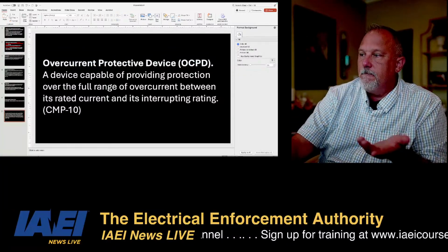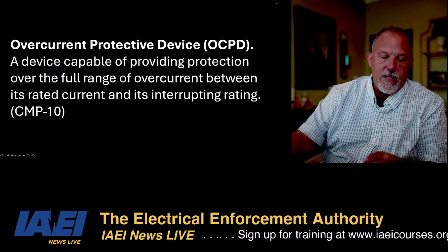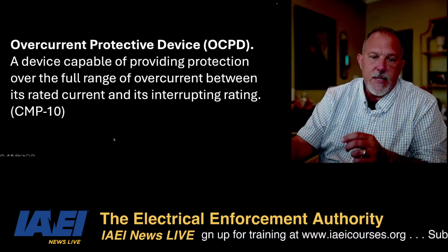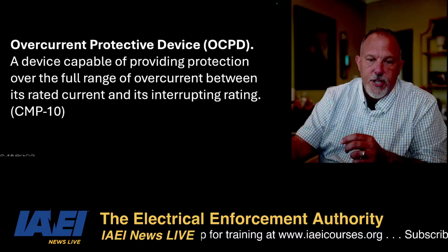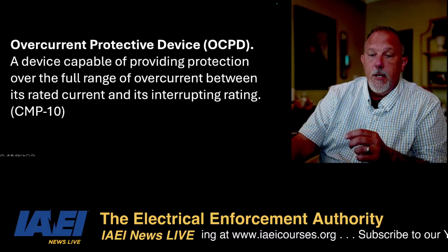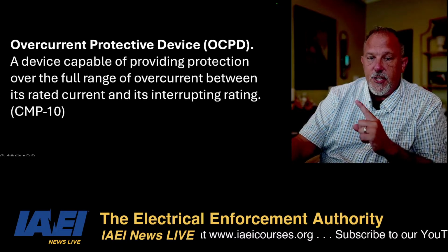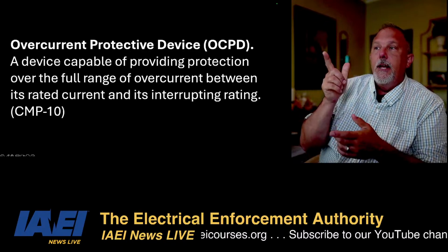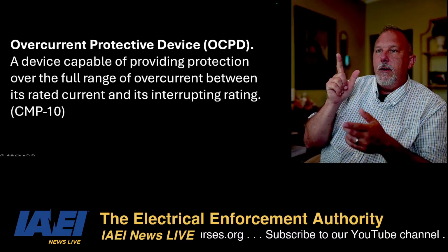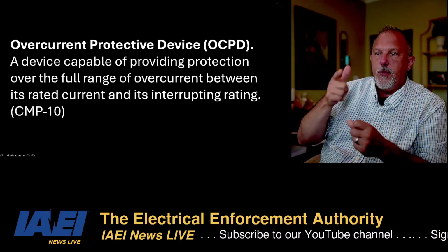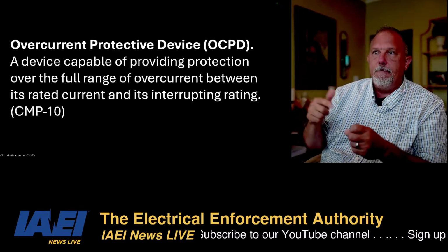We said, look, we feel relatively comfortable that this definition just might do the job for us. So we think this definition just might be what the doctor ordered, so to speak: a device capable of providing protection over the full range of overcurrent between its rated current and its interrupting rating.